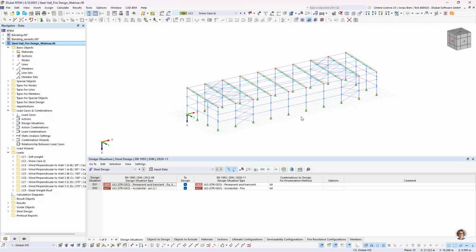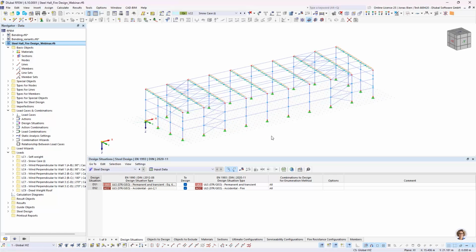Sorry, to the model. And this temperature we could either derive by the standard temperature curve, or we could derive it by some other specification or a parametric fire curve, CFD analysis, whatever it is coming from. We need to make some assumption about to what degree our structure heats up. And then we can apply this temperature load via, for example, a member load.